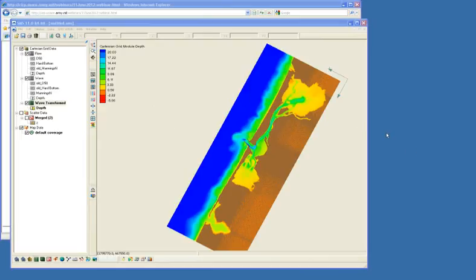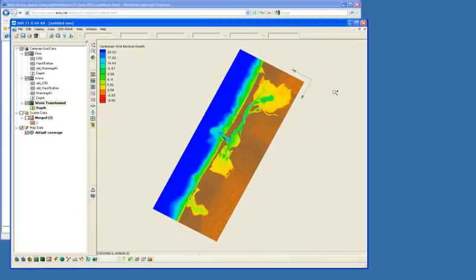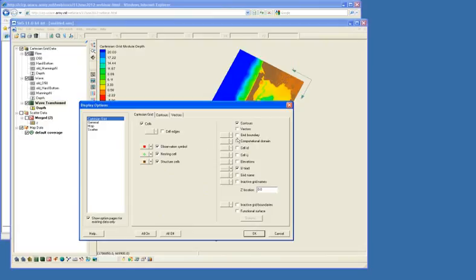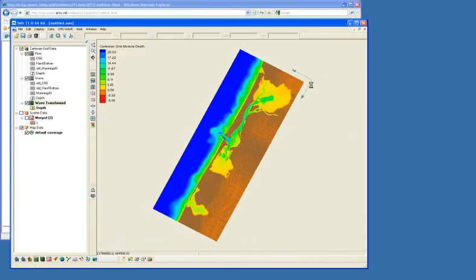move forward here. So the next thing, there's another question that says, how do we bring up the IJ orientation? That's this IJ triad that's located here, that I got from the display options. So it's under display, display options. And for the Cartesian grid, there are several options here, but one of them is IJ triad. And so you just check that box and hit OK, and it'll appear wherever the point of origin is located.